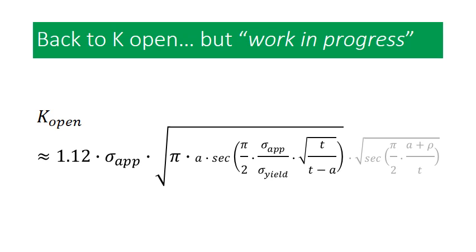And what you have to do there is say to yourself, in the hypothetical situation that we're looking at a blunt crack and we have a lot of ductility, we're actually going to find ourselves in a plane stress scenario. In that situation, we're going to want to use a plane stress toughness, which causes the fracture term in the equation to kind of self-eliminate. And what we end up landing on is just the proportionality of the remaining strength, the remaining strength being proportional to the square root of the remaining ligament.